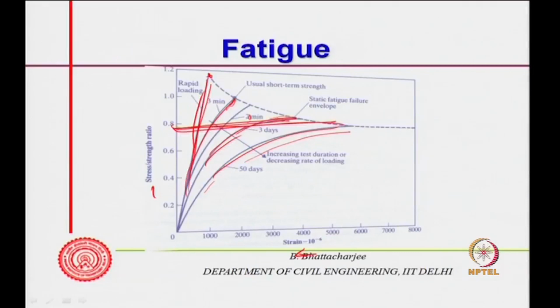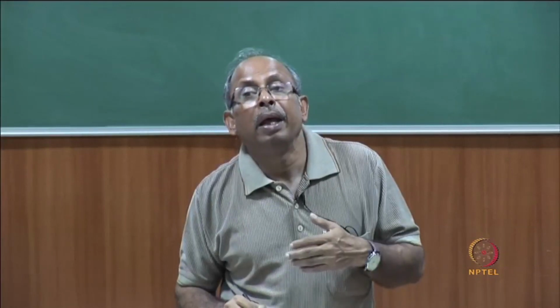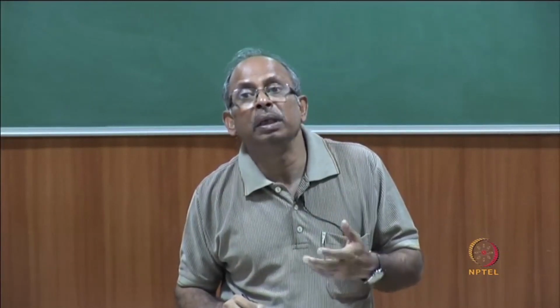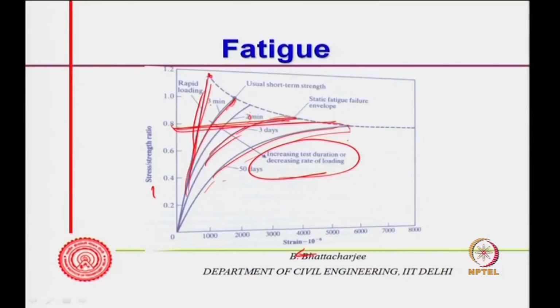So, depending upon this, 3 minutes, 2 days, 3 days and 50 days, increasing the test duration means that I am decreasing the rate of loading, and at a lower rate of loading we have seen that it fails earlier. So, with the same load applied over 50 days, you find that the load carrying capacity is much less.